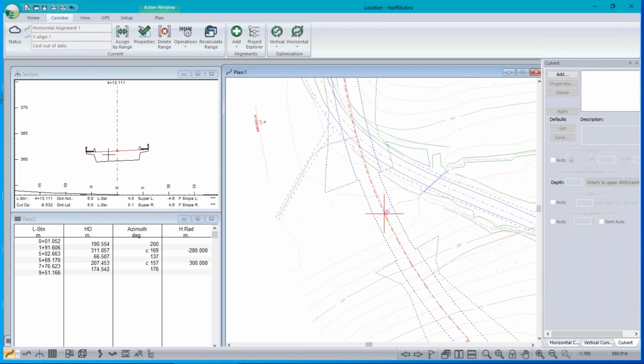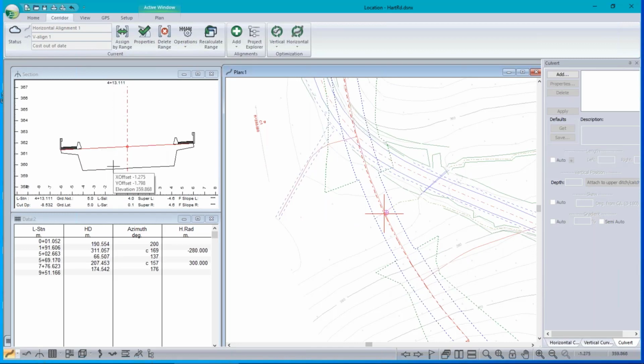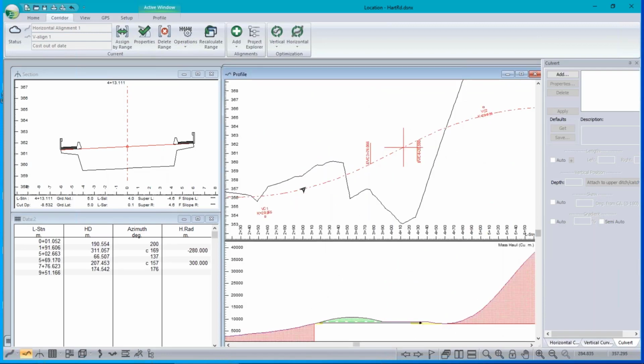And there it is. So I built this template from some of our stock components. There's a jersey barrier there, and a railing on the outside, and the rest of it is a bridge template, which I'll show you in a second. It shows the roadway in the plan, which is a little bit narrower here, and if we look in the profile, no difference. Oh, strangely, there's no bridge abutment there, but it still shows the profile as it was.